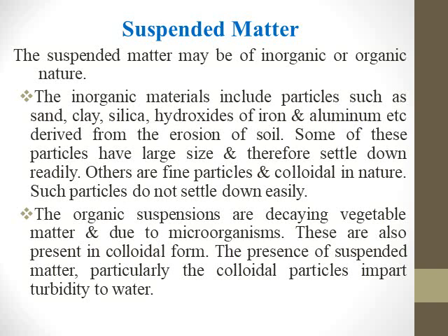Some of these particles have a large size, and therefore they do not settle down easily, and others are fine particles, which may also be in colloidal form. So inorganic materials like sand, clay, silica, and hydroxides of iron and aluminum are present in the water mainly as suspended impurities.